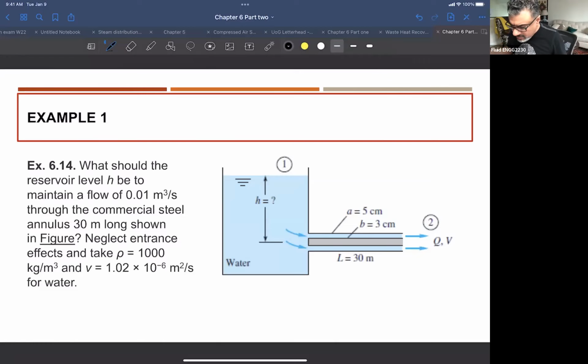Because every point inside the tank has a potential head, plus the pressure head, which is whatever is at the top of these points, plus the velocity head, v squared over 2g, which is 0. That means the level of the tank is your energy at any point inside the tank, right? We'll talk about this when we discuss hydraulic energy and gradient lines, okay?